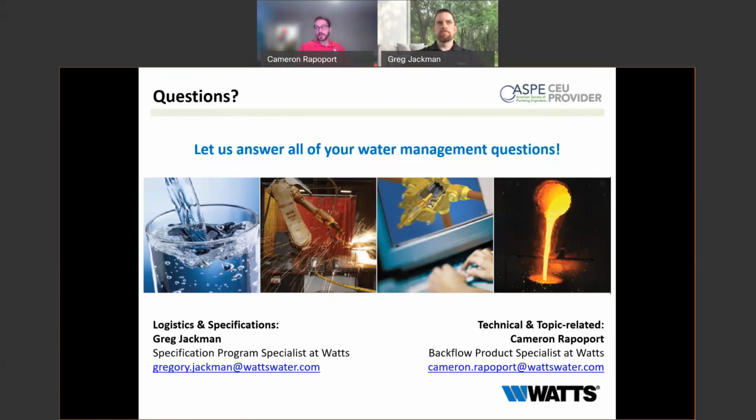But if you have to make repairs, and those repairs might be extensive, and it might render the system inoperable for a long period of time, I would talk to your fire officials about how to handle that, or at least talk to the building owner. Because like I said, usually if your fire system doesn't work for an extended period of time, you've got to get a fire watch. So yeah, I would do some research. I'd talk to your fire officials.